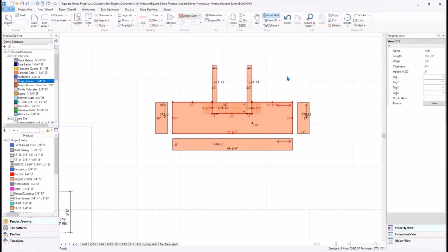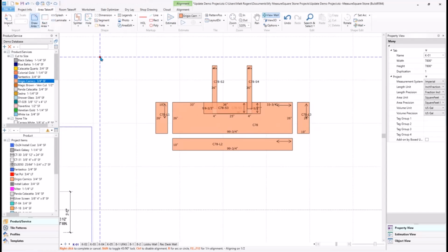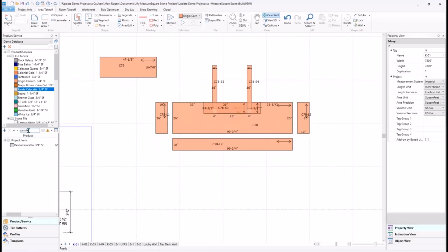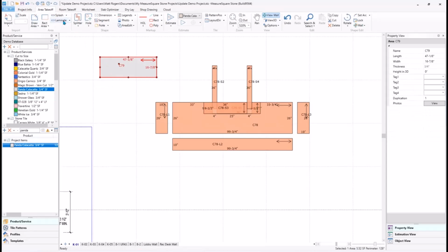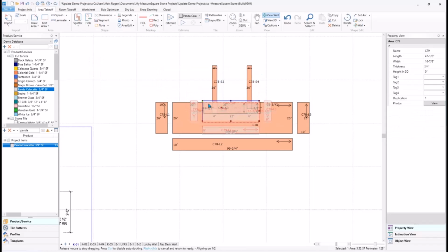So let's actually do that real quick. I can actually create the mantle. Let's do that as a separate material so it's a little bit easier to see. I'm going to create this as a separate piece right here. We'll make this white. I have this in the project already, so we'll drag and drop that in. And then for this mantle, I'm going to use the laminate piece again to wrap this around. We can change the depth of our laminate or the width of our mantle here. Let's make that 6 inches. I'm going to drop this back onto this piece.